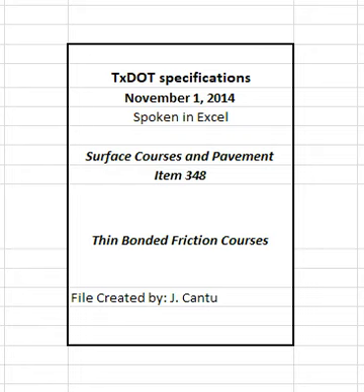Use department-provided templates to record and calculate all test data, including mixture design, production and placement tests, control charts, and thermal profiles. Obtain the current version of the templates at http://www.txdot.gov/inside-forms-publications/forms-site-manager.html or from the engineer.